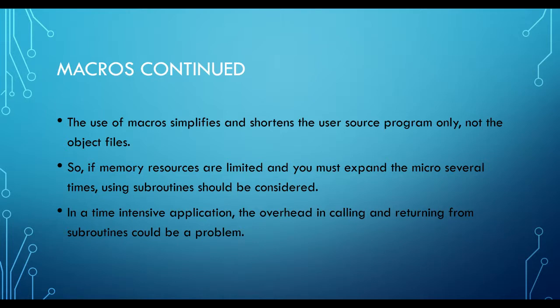Okay, this is very true. Every time you call a function, there is an overhead time. So you spend a little bit of overhead when you are calling a function or a subroutine. But other than that, the advantage is that it makes your life much more convenient. If you develop an embedded system and you really want to minimize on the function, you can do so without the function, because every time you call the function, there is an overhead time.